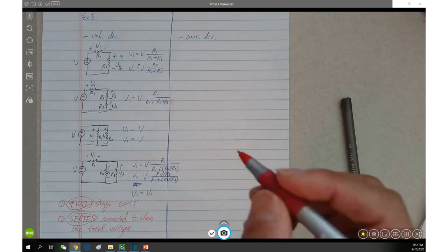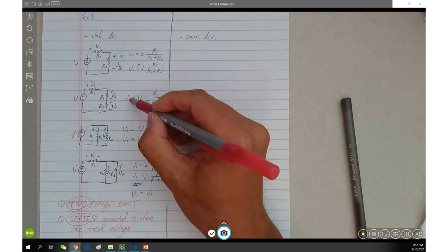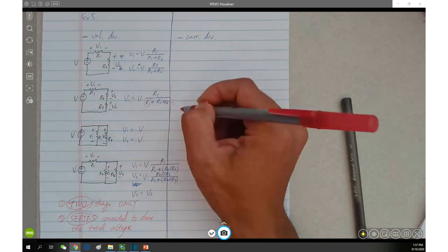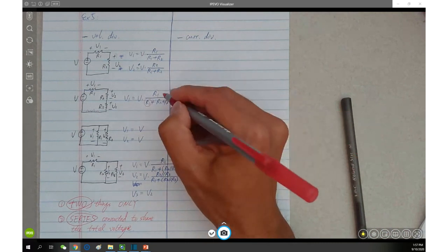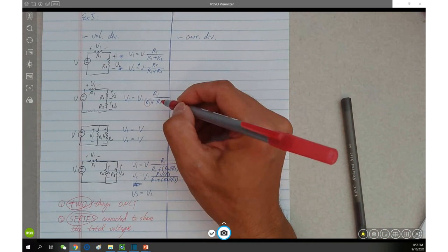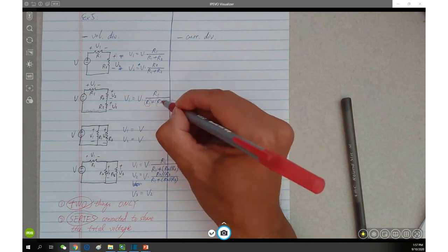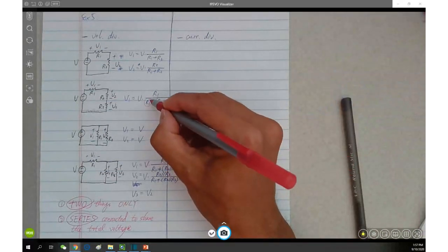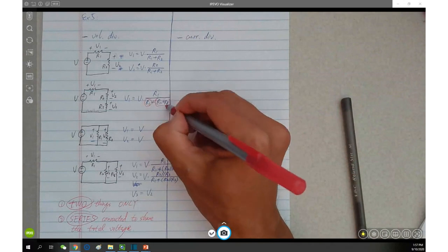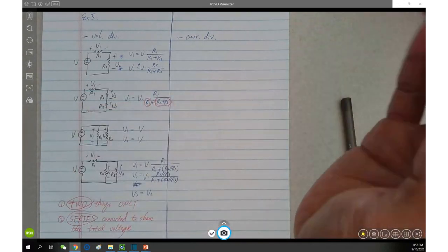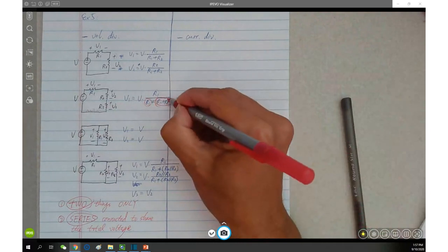What it means is you're looking for the V1 and then you need to keep R1 here in the denominator. Combine the rest of the two, which is R2 and R3. Since R2 and R3 are series connected, that's why you have R2 plus R3. So again, your denominator only stays two things, summation of two things, no more, okay? Even though you're seeing R1 through R3. However, the idea is you're combining R2 and R3 first.